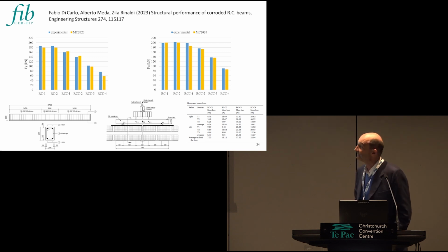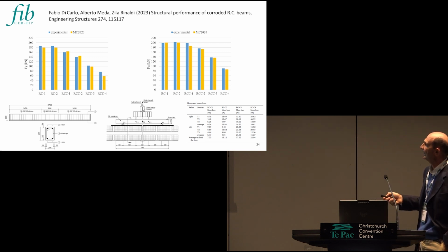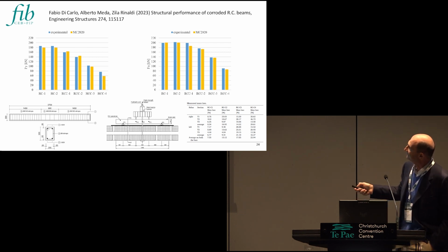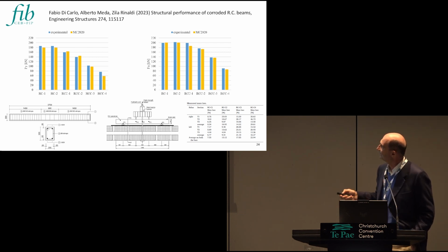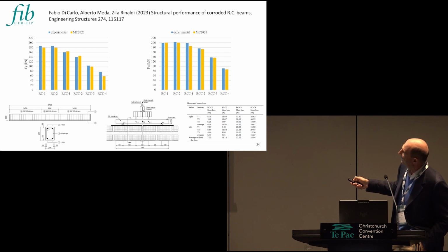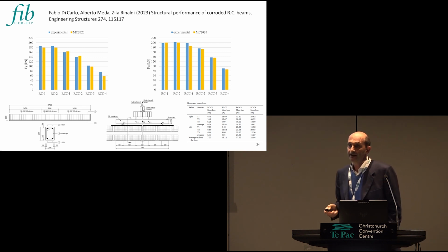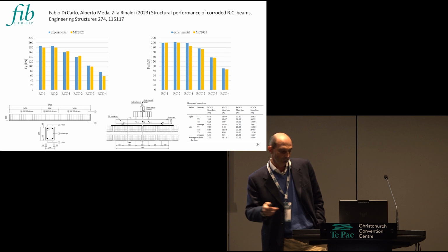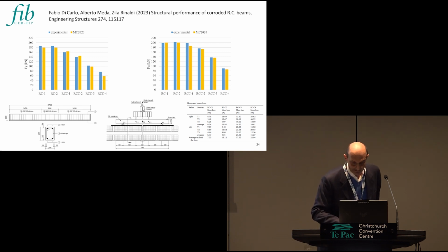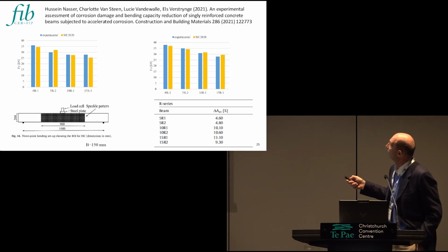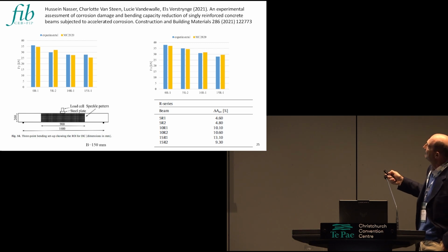So we started an activity taking a lot of data from the literature. Those are the tests that I presented in this conference, and you can see how the experimental result and the capacity, the yielding capacity of the beam and the ultimate capacity of the beam, fitted well with the model presented in the model code, but not only with my test, but a lot of tests available in the literature recently published.